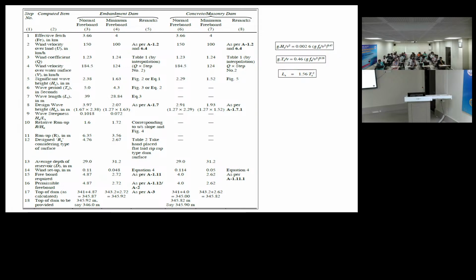See, what is FRL? By definition, by name it's full reservoir level. But what does it actually represent at the site? FRL, full reservoir level. That means when the gates are closed, we are maintaining the reservoir at a particular level throughout the year. Let's say there is no spill from the spillway. So that level we maintain as FRL.